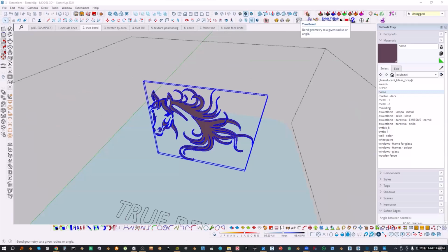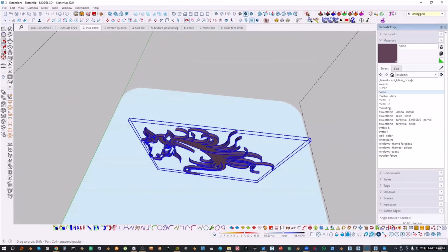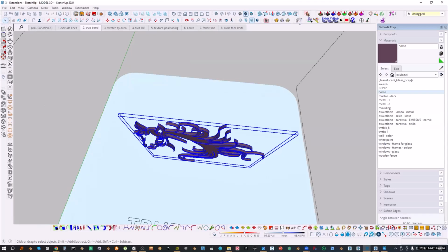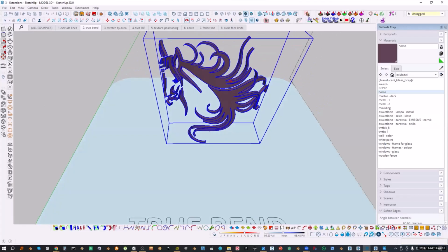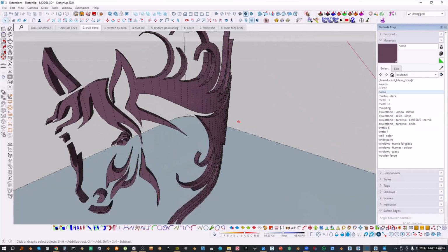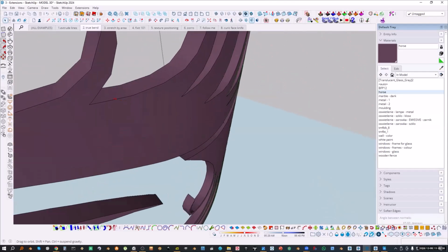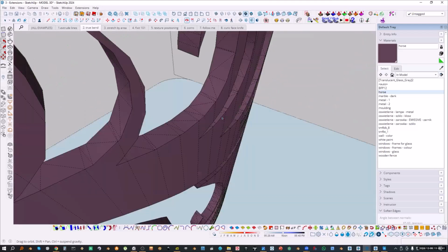I'm going to select, this is the icon, True Bend, which is another free of charge plugin. All the plugins I'm presenting are actually free of charge today. And not just today, but always. So True Bend. And now I have those dots. If I want the bending in a more detailed way, I can type in 50S, which is 50 segments, enter. And now I can just grab it and type in maybe 120 degrees angle, enter, and enter again. And now it nicely bent the geometry, with the hidden geometry, which I have on the V key. You can see that it created that nice shape.